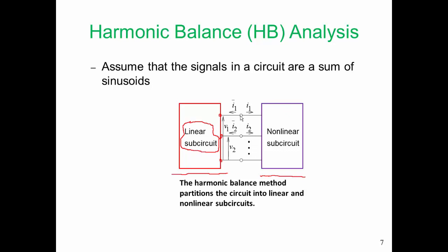And at these terminals, one here, 2, 3, we're going to assume that the signal can be represented by phasors. So we can express these as voltages V1, V2, etc. Then, assuming a voltage, let's take V1, assuming the voltage phasor here, we calculate the current flowing into the linear circuit. All we have to do is multiply out the Y parameter matrix, and then we do a nonlinear simulation to calculate the currents flowing into the nonlinear circuit.